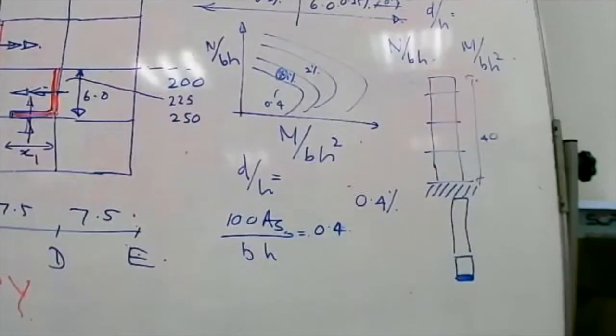The reason is there are plenty of shear walls and the deflections are very small. So all the things will be dominated by the behavior of the shear wall, where the shear wall deflection will be very, very small, like 5 to 10 millimeters, which can again be ignored, and the frame will be designed separately.